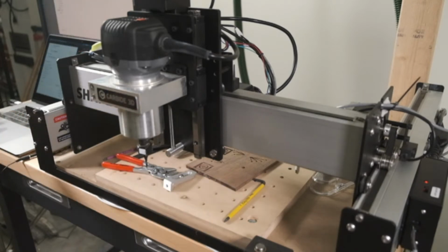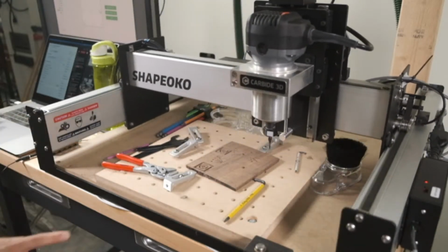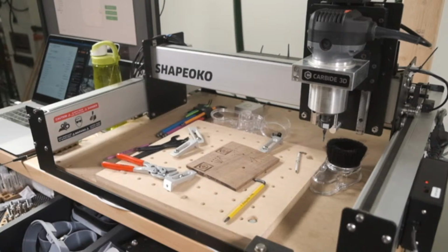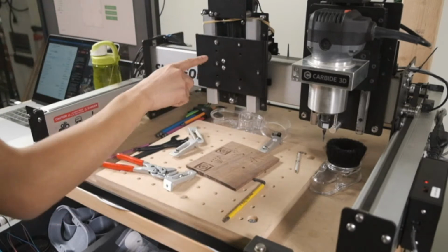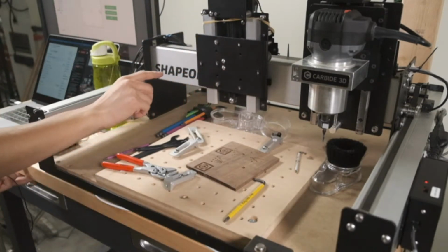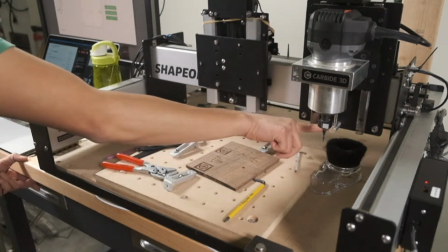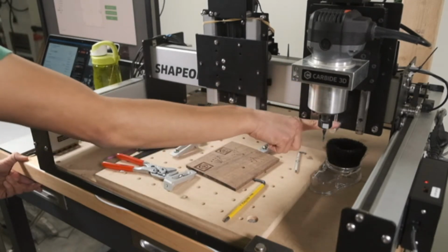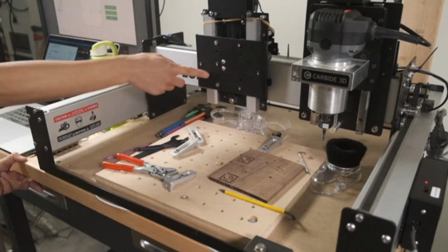What else do I have? Let me jog this machine over and talk about something that people often don't consider when they're using the stock belt drive. So this is the stock belt-driven Z-axis that we currently have. This is the Z+. The Z+ has a hard stop. So there's a little stud here that prevents the carriage from overextending and coming off the linear rails. The belt-driven Z-axis does not have that.